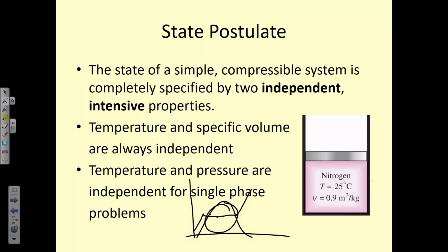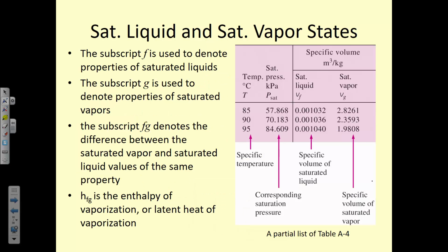So they can't rely on one another, and they have to be independent of the size of the system, or intensive properties. Okay, so you can't use mass to define all the other properties of your system, because mass very much depends on the size of your system. And as we said before, we can define our system boundaries anywhere we want, and depending on where we define that boundary, our volume and our mass will change, okay? But intensive properties won't. So if we have to have a system defined, no matter where we prescribe the boundaries, we need to find properties that are independent of that boundary prescription. So this is review again from last year, but maybe you didn't learn it the first time, I don't know.